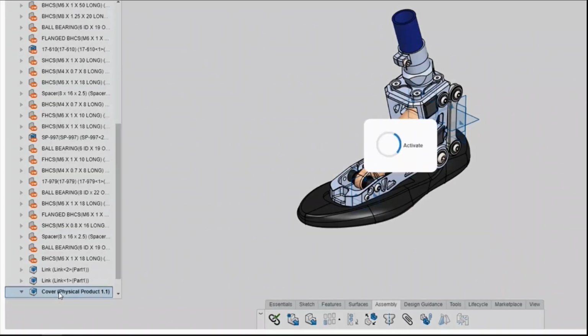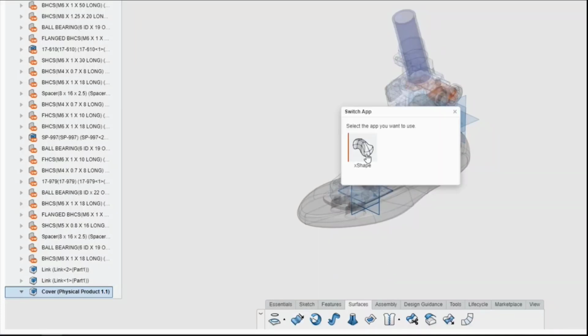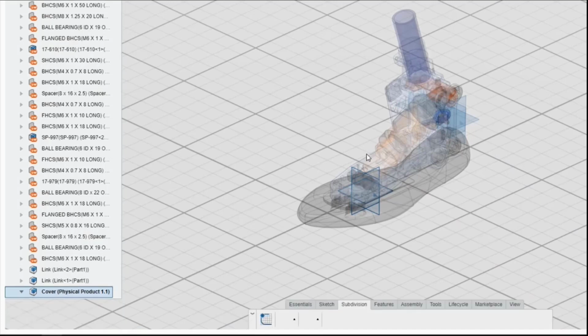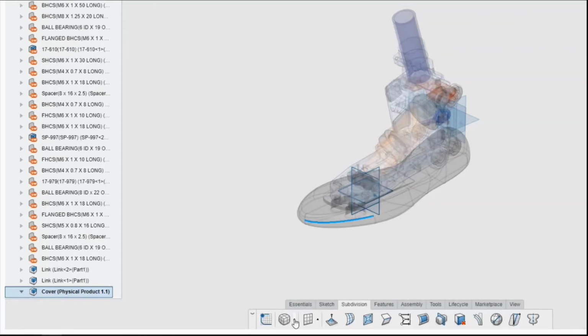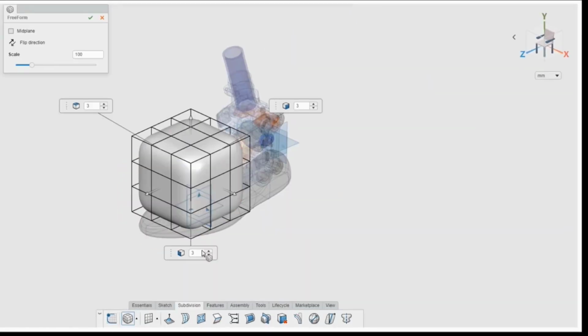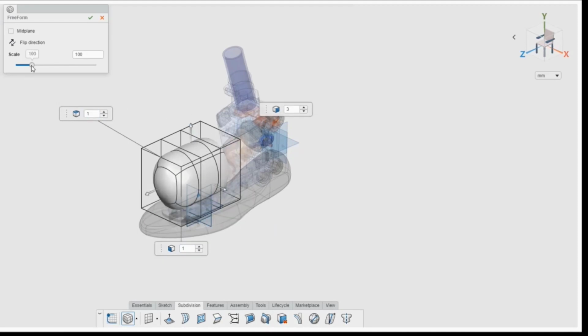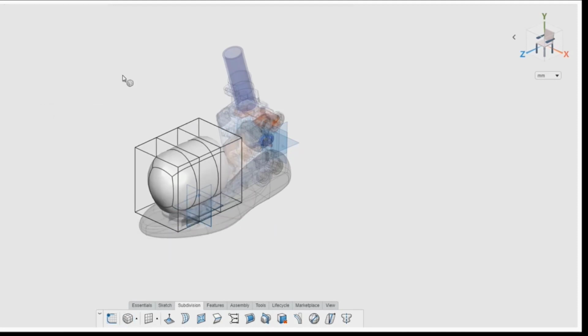Well, so here I can use the surfacing tools as we have in SolidWorks, but she told me to use the X-Shape, the Sculptor. I'll showcase the tool. So this tool is very robust. You can use all the primitive shapes like box, cylinder, and all. You can simply place it here. You can add the number of elements you're looking for. You can customize it according to your requirement by using the push-pull method, the scaling options, and all.